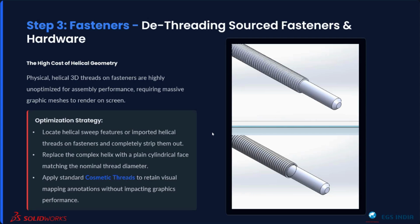By either just adding an extrude on top of your thread or by recreating the component with cosmetic thread, you'll be able to save a lot of graphics triangles from entering your top level assembly for one specific instance. But all of this can be multiplied, and the impact would be multifold when it comes to multiple components being used in your top level assembly over here.